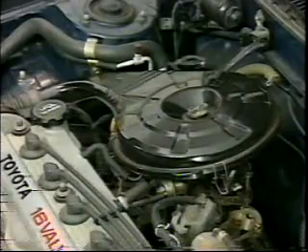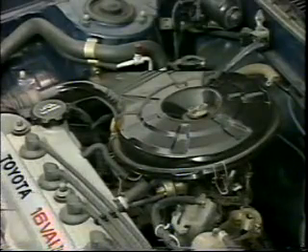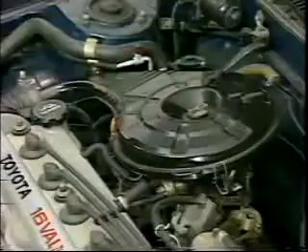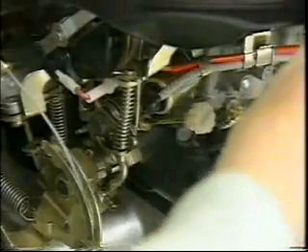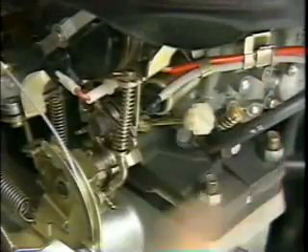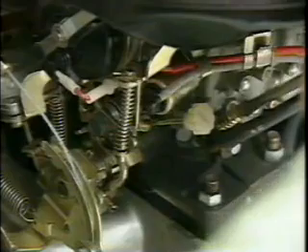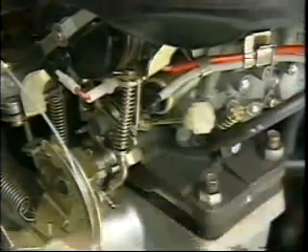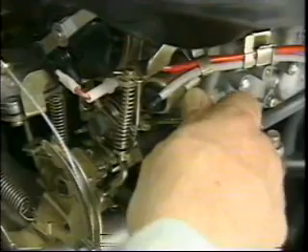In models with an air suction hose to the air cleaner, remove it and plug the end with a hose plug. Turn the idle mixture adjusting screw to raise the engine RPM to its highest permissible idle setting. Then, turn the idle speed adjusting screw to set the idle to the specified idle mixture speed. Repeat these 2 steps until the engine RPM no longer goes above the highest permissible idle setting. Finally, turn the idle mixture adjusting screw to set the idle speed to the specified setting.